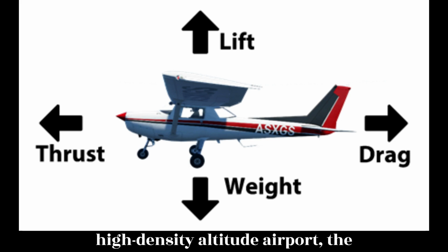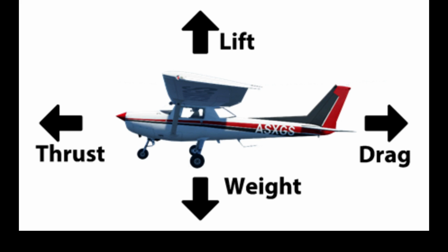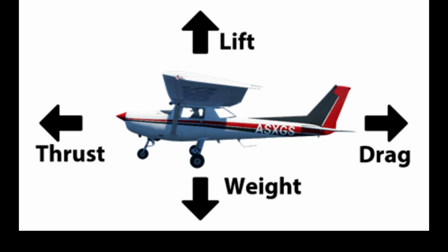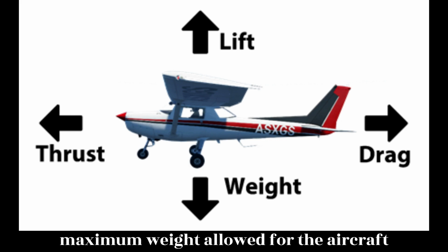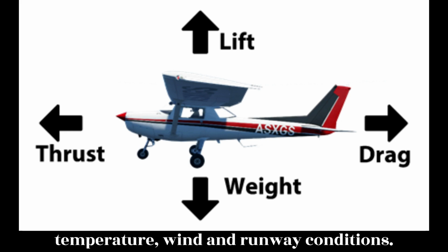When operating from a high-density altitude airport, the pilot's operating handbook, POH, or Airplane Flight Manual, AFM, must be consulted to determine the maximum weight allowed for the aircraft under the conditions of altitude, temperature, wind, and runway conditions.